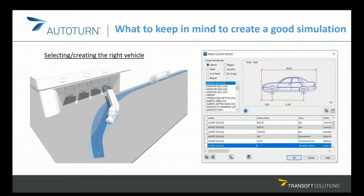So as we have understood the importance of swept path analysis, how it is done, and the major factors influencing the swept path of a vehicle, now let's see how we can create a good simulation. The foremost important thing in creating a swept path is the vehicle selection. We should always select the right vehicle in order to be able to perform an accurate analysis, rather than assuming a larger vehicle will do the trick.